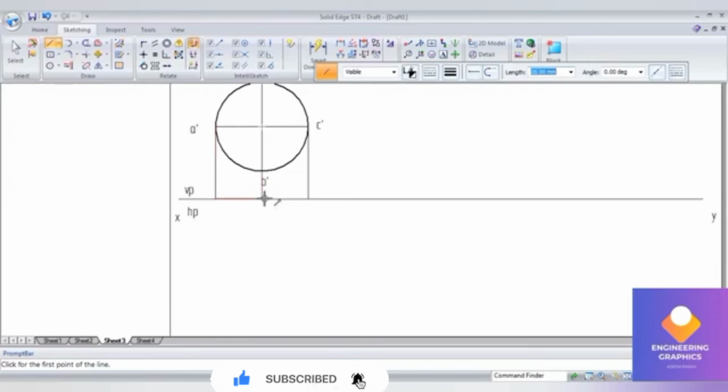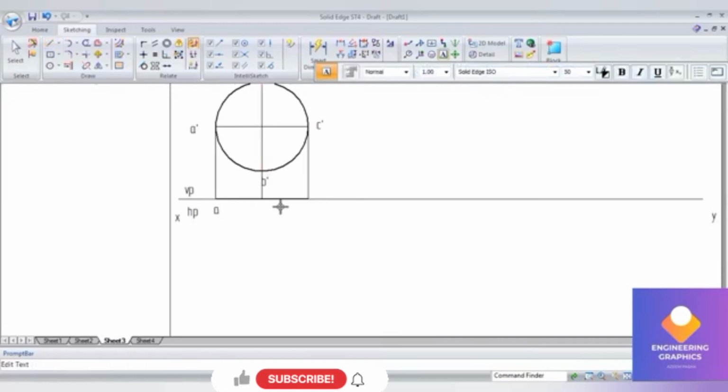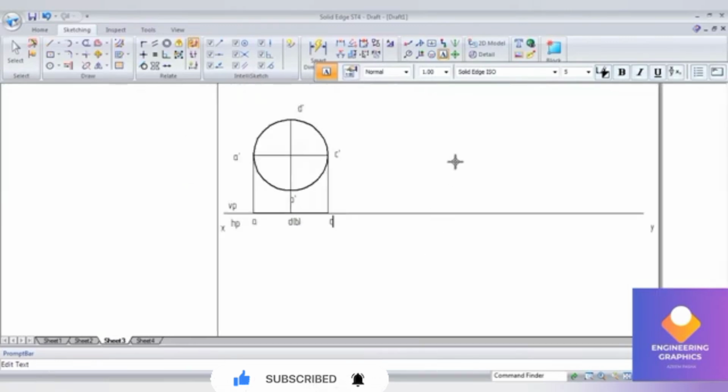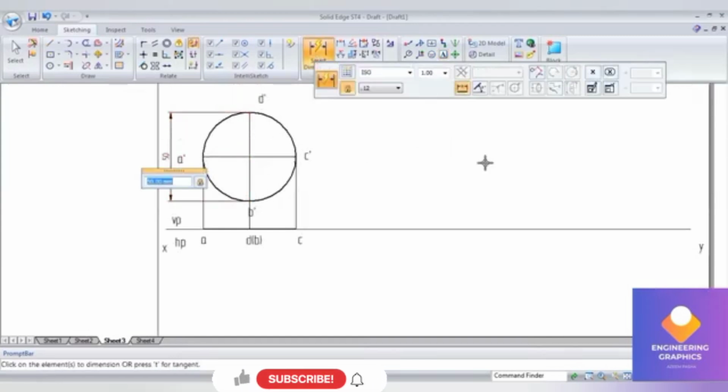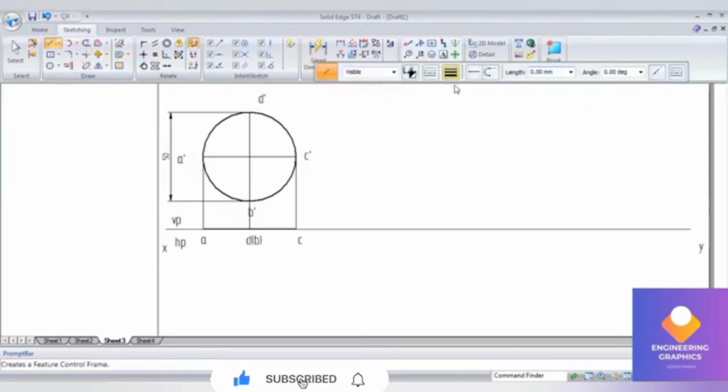So here in the top view, I'll be drawing with the thick line from one end to other end. So it will be easy for us when we draw the second position inclination, because in this problem he has not given any kind of inclination. He is just telling that we need to use the major axis and minor axis dimensions to construct the ellipse here. So what I will do is, for the major axis I'll be projecting horizontally,